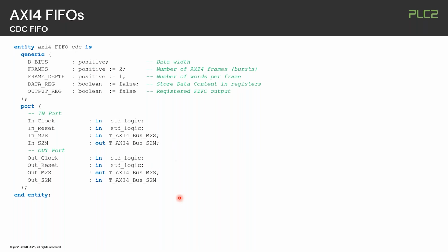We also have internal discussions on how we can go forward in the direction of VHDL 2019, providing this as real interfaces with mode views. Then we can reduce it completely to 1 input and 1 output port. What you can also see here is that we are not specifying any sizes on the AXI Lite interface itself for bit sizes, so it's a generic interface and can work with any bus size. And then we have here the specification for data bits and number of frames.